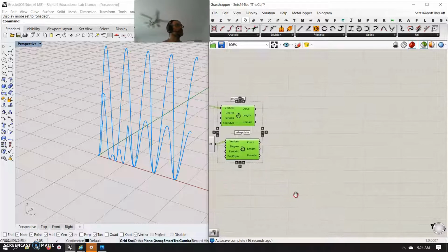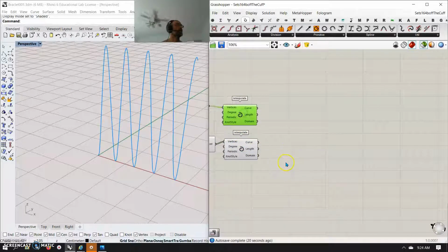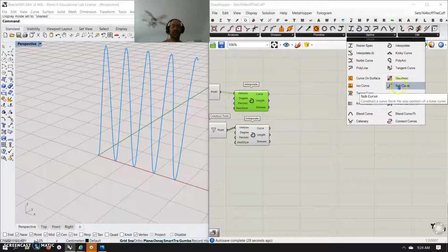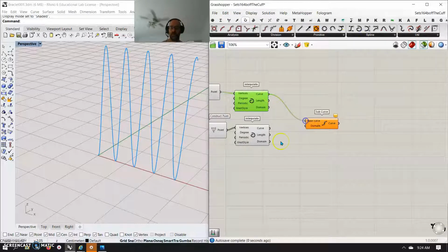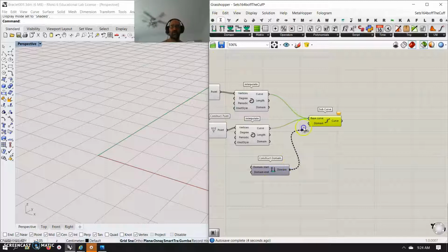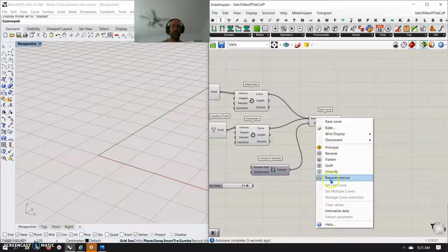So we're sitting at 6 minutes, and we should be fine on this script. So what I'm going to do is take those curves and do things with them. I'm first of all going to take those curves and put them into a subcurve. So let's go into curves, spline, subcurve, because I want to be able to slip it on my wrist. So let's take those two, and let's take a little domain out of here, subcurve, and let's set the top part of the domain to 0.9. In doing so, I'm going to have to reparameterize my base curves.